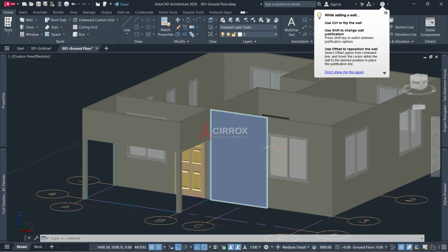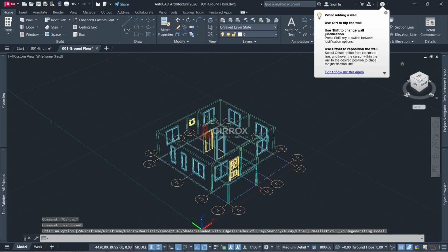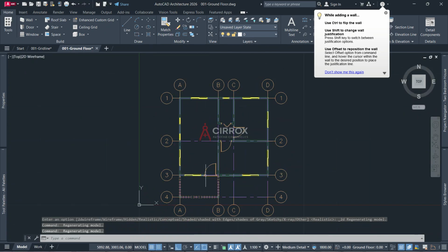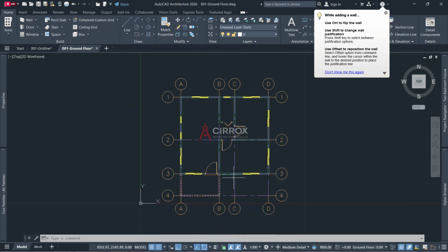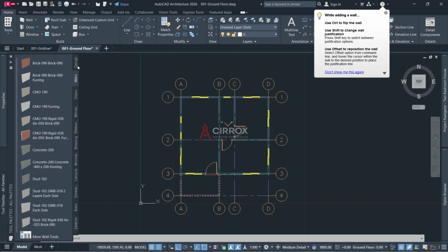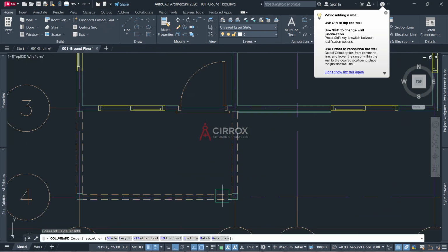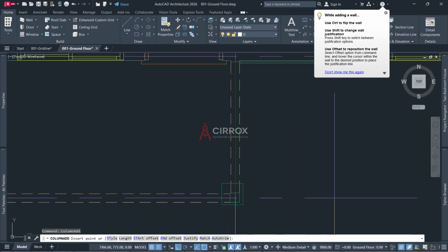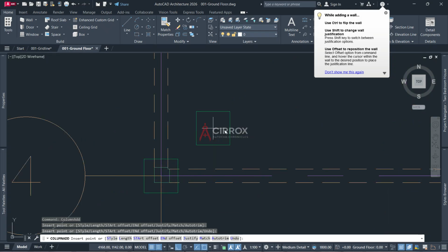Okay, so head back to the wireframe, top view, and now that we have our walls fixed and our design done, we are actually going to add in a column over here. I'm going to go back to palette, then design, and we click on column. The columns, we'll put it in here, put one there and the other there. So we are actually going to fix it.